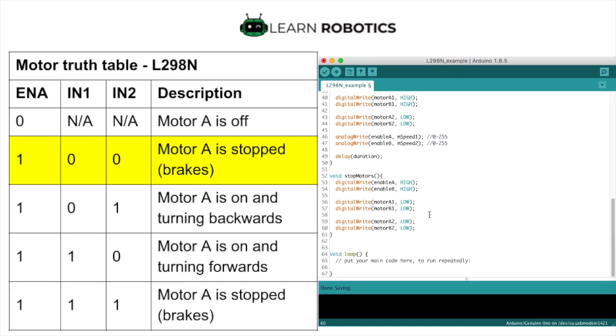So if you wanted to stop the motors and disable them, you could write a 0 to the enable pin instead of a 1 to the enable pin, or you can contain that in a separate method called like disableMotors or enableMotors and use that throughout other methods. The idea behind writing these methods is to obviously reduce the amount of lines of code that are repetitive. And so by having a very simplistic method that you can reuse, it makes it a lot easier when you try to add more complex functionality.